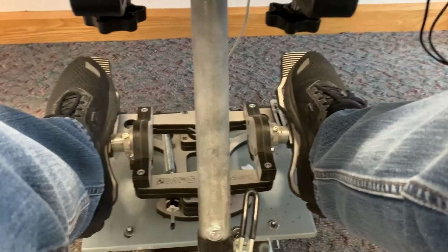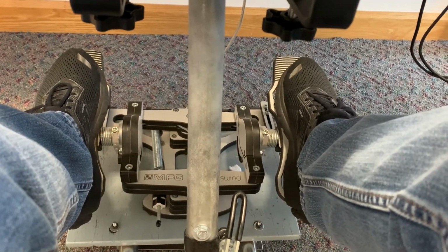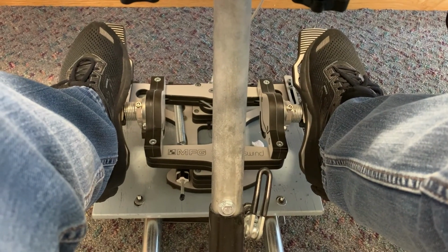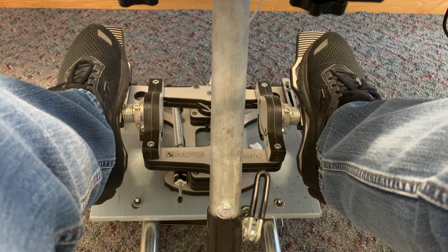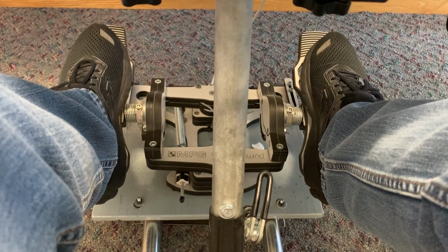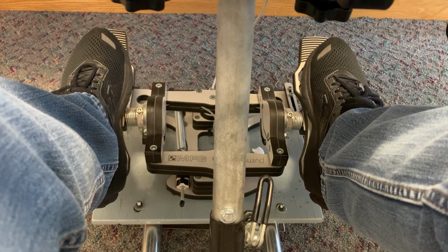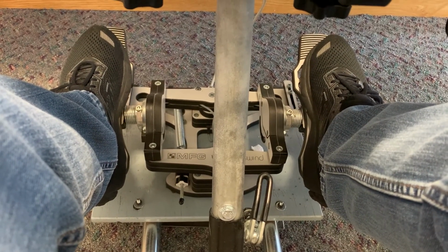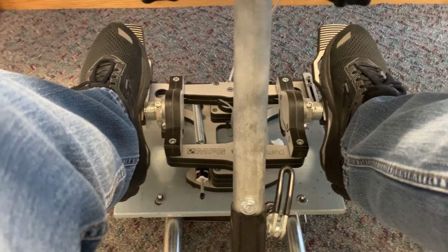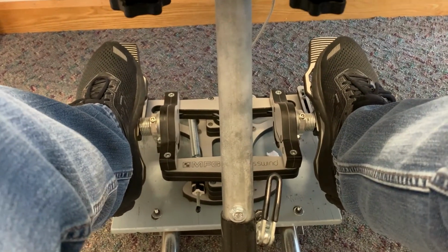The tops of the rudder pedals will push forward individually, applying brake pressure to that pedal's respective wheel. The left pedal controls the left brake and the right pedal controls the right brake. Apply equal pressure to both brakes to prevent ground looping and to come to a straight, complete stop.